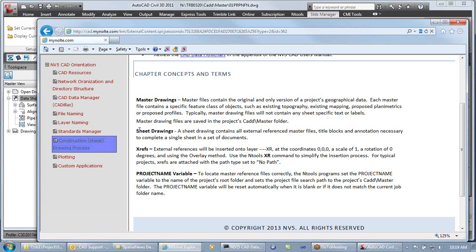Because of this, one thing you're going to find is that when we work with entities, we do not assign colors and line types directly to entities. Everything we do is by layer, because when I XREF something, I can manipulate layer properties. So I can have my water line be blue in the water line plan, but if I want to fade it back in my sewer plan, I can make it red, and that'll be a thinner line weight in the sewer plan. But I can't do that if I've assigned a color directly to the entity. So everything should be on the appropriate layer, and then we manipulate layer colors and line types to control the display.